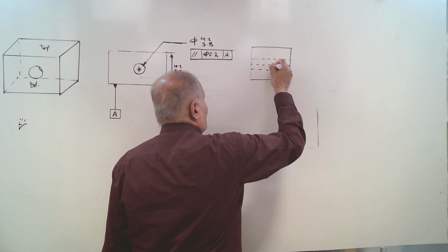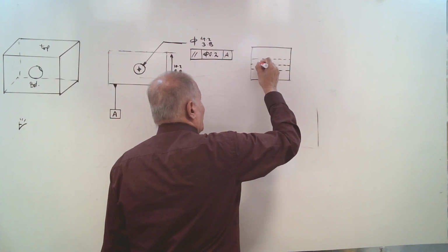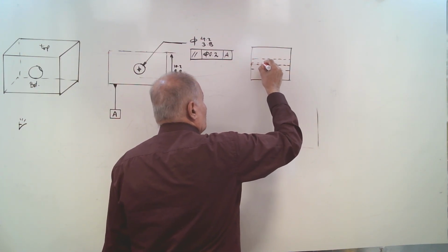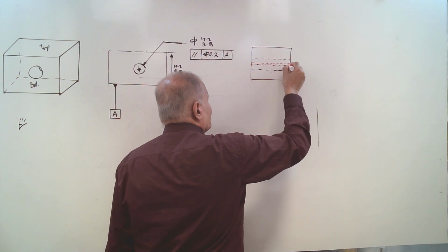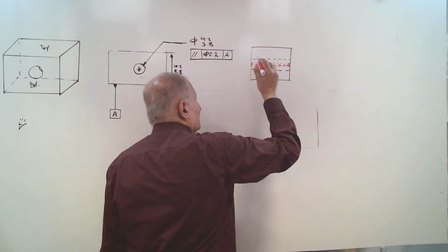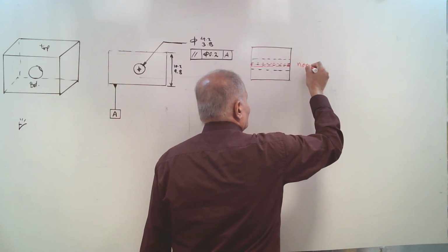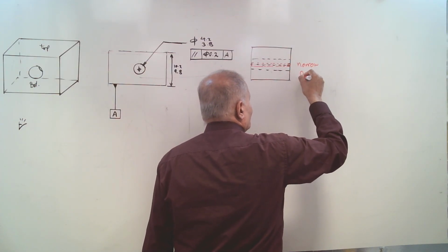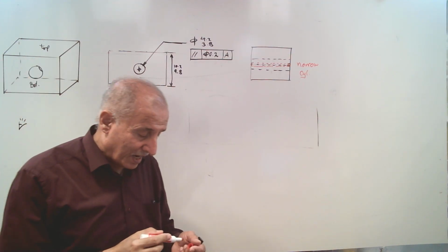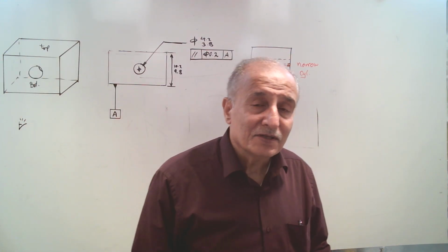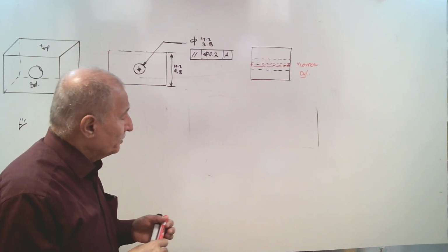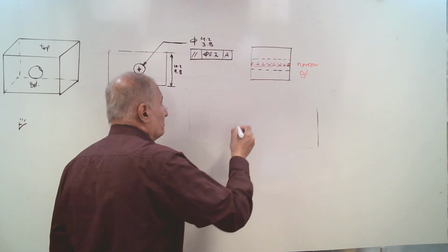This set of derived median points that represent the axis of the hole must lie within a tolerance zone, which is a narrow cylinder. Is the zone shape here for the axis. Narrow cylinder. This narrow cylinder must be parallel to datum A.